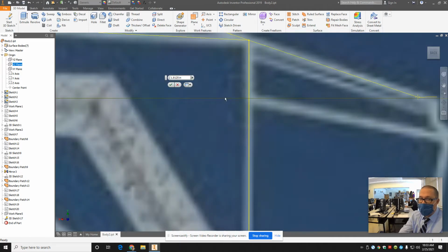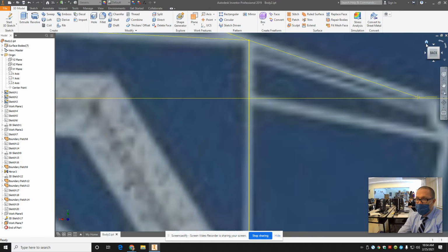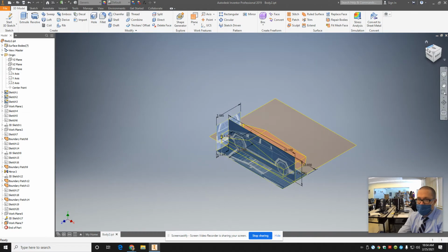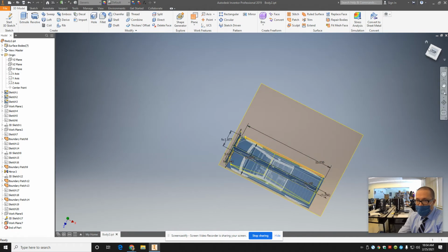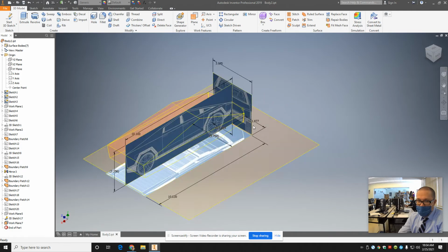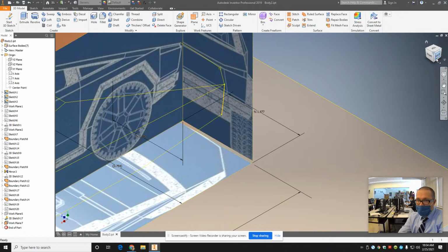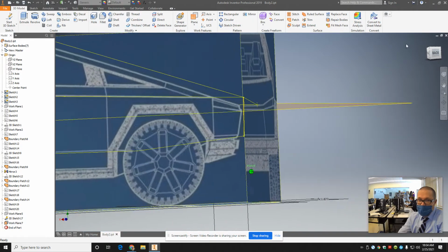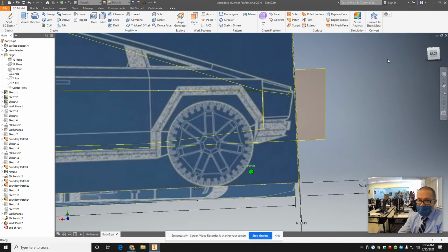Yeah. Adding that work plane? I dragged it up to about there. If you need to get it in the right position, you can adjust this number manually. Mine happened to snap just about where I want it. So hit OK. Now this work plane cuts through those included geometries, okay?